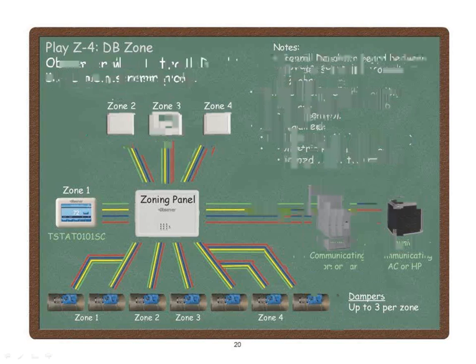The thermostat itself self-configures when you power it up, which is beautiful. It finds the equipment if it can. If it's non-communicating equipment, it asks you questions. It asks you what accessories you have, and then configures all the airflows and everything related to all the stuff you just answered. It's beautiful.